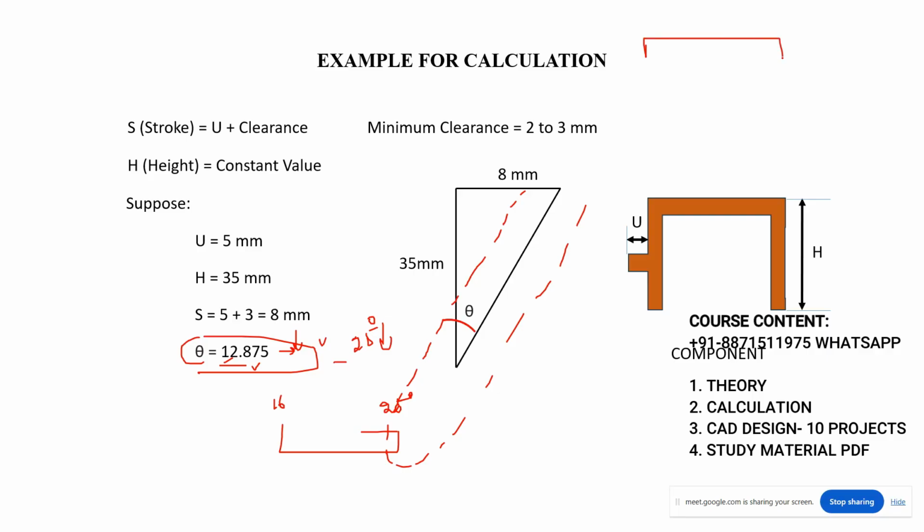Just for an example, you have a mold like this. See here, this is the cavity and this is the core. Now here, for example, you are using the angular pin, but there is a limit for increasing the length of this, right? You cannot take the length of the angular pin like this. Right or wrong? So there is a limit for that.